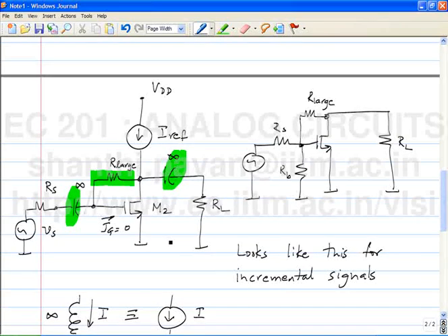What else does it depend on? Triode operation is defined as what? That if the transistor has to go into triode, the drain has to go below the gate. So obviously the limit better depend on both the quiescent value of the drain as well as the gate.